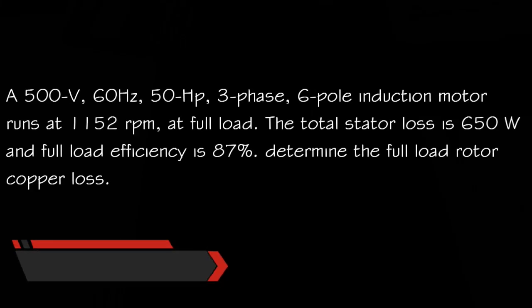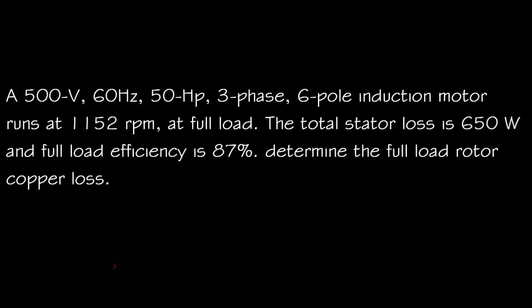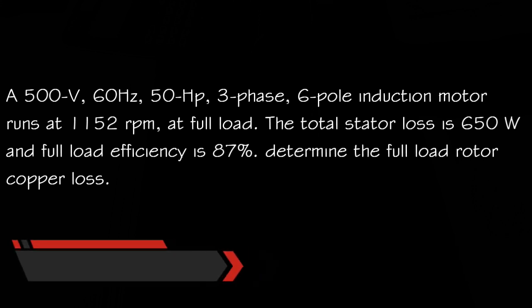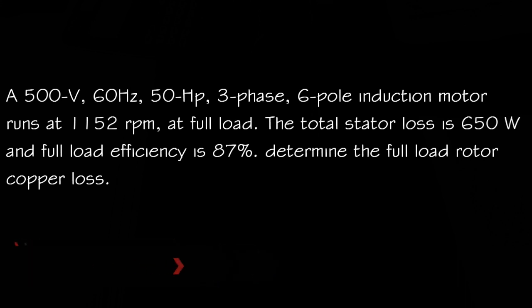The eddy current and hysteresis losses of a 4000 volt 60 Hz single-phase distribution transformer are 280 and 560 watts respectively. Determine the core loss when the transformer is connected across a 4600 volt 50 Hz source.